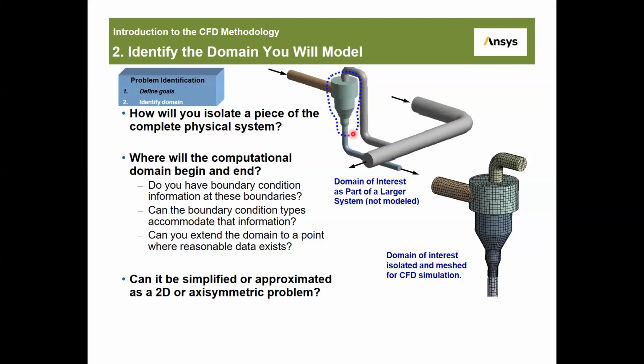If you want to analyze this part, then you need to cut. You just draw this part, we do some meshing, and then we analyze. Then you need to identify the inlet: if I cut here, the inlet becomes here. And if I cut here, the outlet will be this part and also this portion. This is the outlet, and this is the inlet.